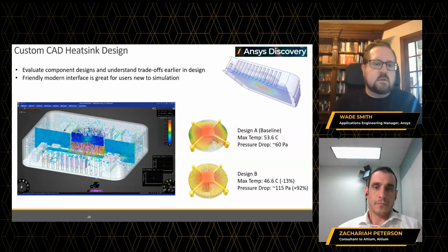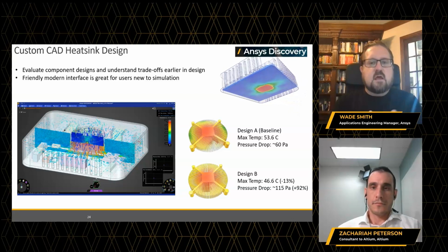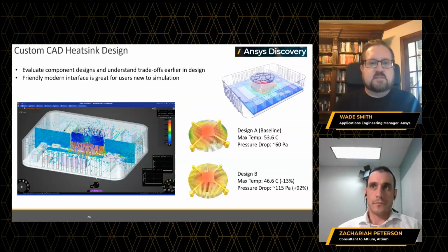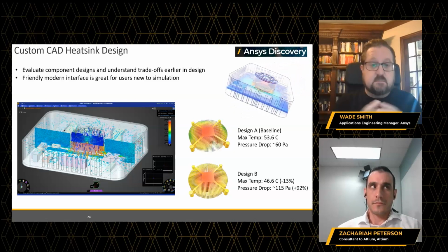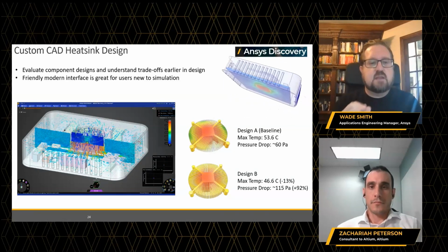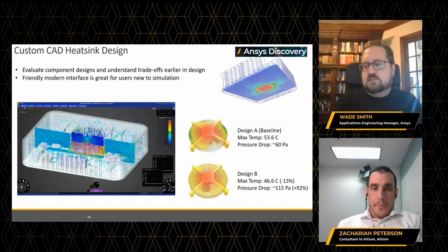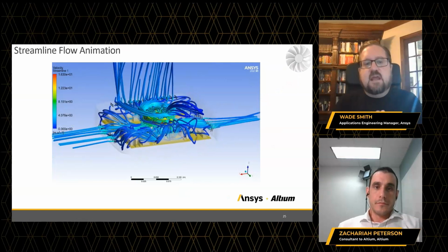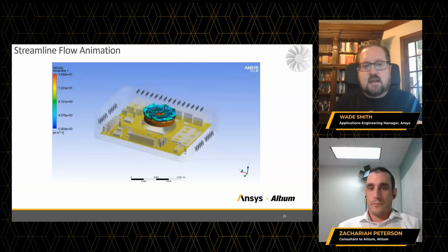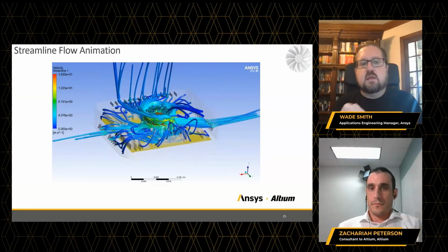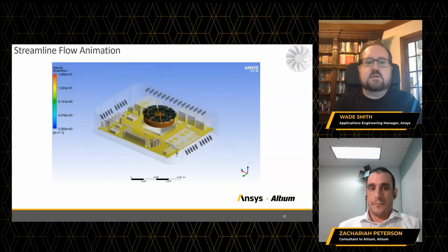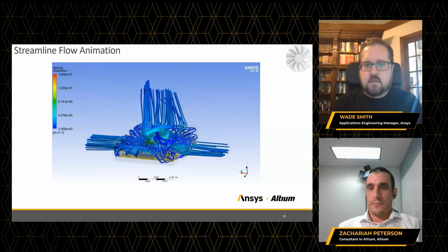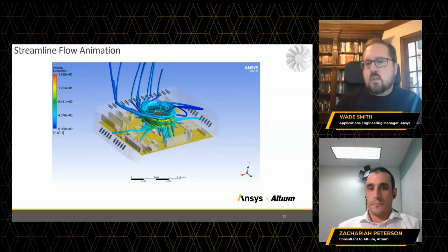So we can use a software called Ansys Discovery, which will allow us to optimize this geometry in real-time simulation. So as you change this, the simulation's changing, and it gets you an extremely fast way of optimizing this geometry. And taking this back into IcePak, we can add the fan and now look at the exact airflow through this system, so we can modify the holes in the enclosure and the holes for the air intake and figure out exactly the best way to cool this system.